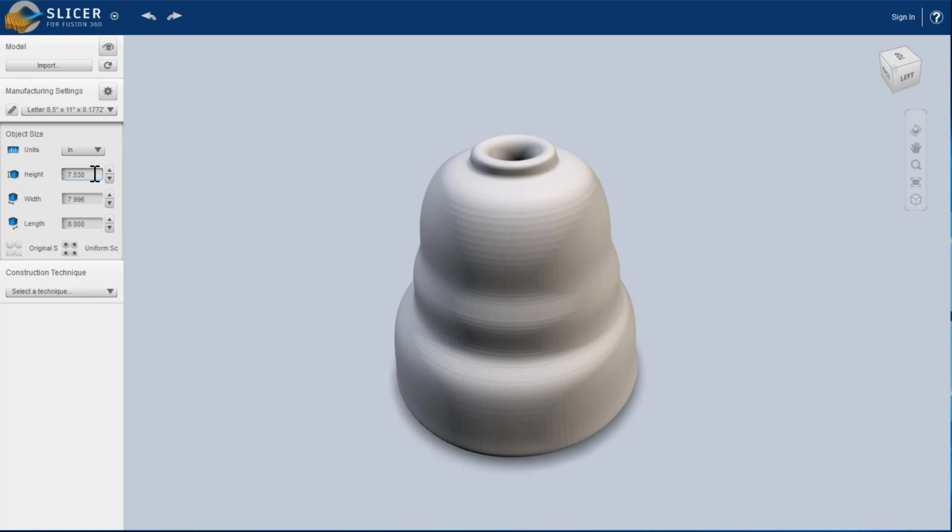Before you export your model from Rhino, you should scale it to the real life size that you would like to make the model. So this, before you export from Rhino, instead of working at 1 inch equals 1 inch, you would scale to, say for example, 1/8 of an inch equals a foot, and then determine exactly how big your model would be. Maybe it's going to be something like 2.5 inches tall, and you would just want to confirm that these dimensions are correct.